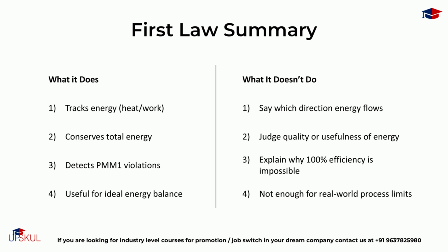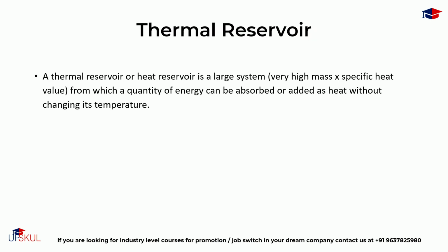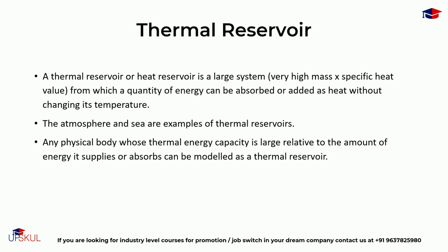Before we study the second law, let's discuss some thermal devices and their performance, which will help us understand thermodynamics better. The thermal reservoir. Now, a thermal reservoir is a large system from which a quantity of energy can be absorbed or added as heat without changing its temperature. The atmosphere and sea are examples of thermal reservoirs. And any physical body whose thermal energy capacity is large with respect to the amount of energy it supplies or absorbs can be modeled as a thermal reservoir.